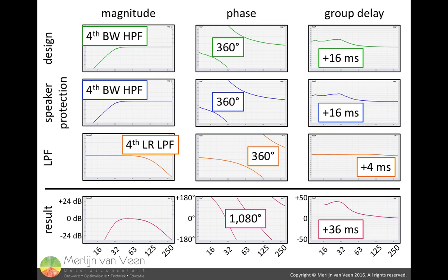As a result, the entire operational range of a typical subwoofer occurs over a 1080 degree phase span. This is the reason why subwoofers aren't capable of delivering a single frequency at the same time. The subwoofer has become a stretched function of time. They're typically stretched out over dozens of milliseconds, as can be seen in the flashing box.